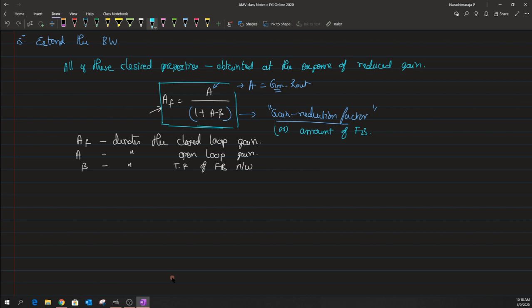Okay, and again I try to bring out one important point: it is not implied that when this negative feedback circuit becomes a positive feedback circuit, it always leads to instability. In fact, positive feedback is useful in a number of non-regenerative applications like filter designs. Okay, so anyhow, these are not part of our syllabus as of now. I just want to bring out that not all positive feedback circuits lead to an unstable amplifier design. Sometimes one could use positive feedback in a properly controlled environment, and then utilize it for the design of non-regenerative circuits like filters.